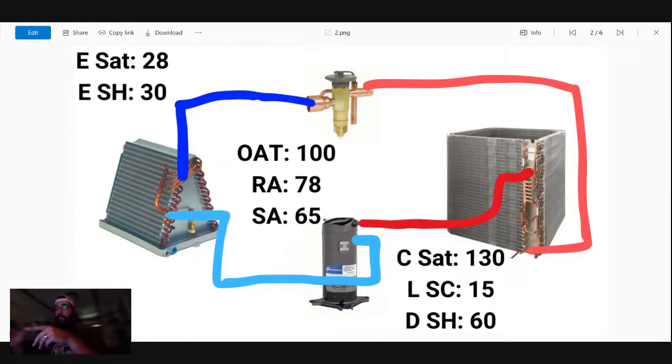Okay, so sensing bulb loose or uninsulated, that is another kind of visual inspection. You check both of those, and the bulb is insulated, and you are satisfied with the mounting procedure they used. It's good and tight on the pipe. There's not a lot of corrosion around it.